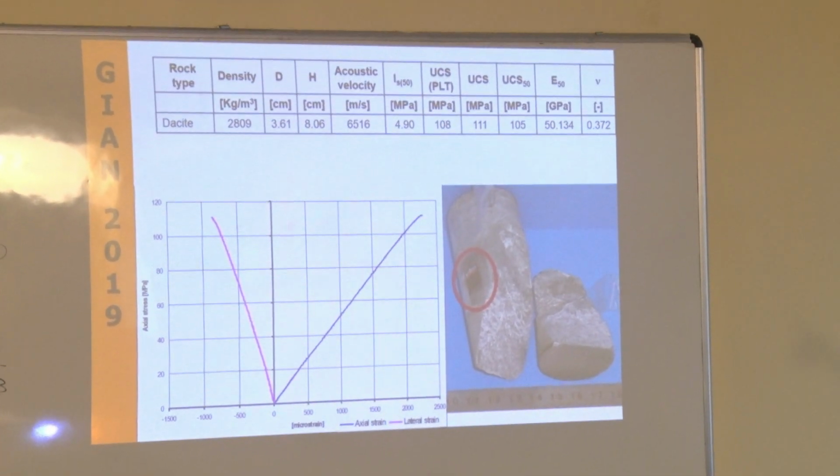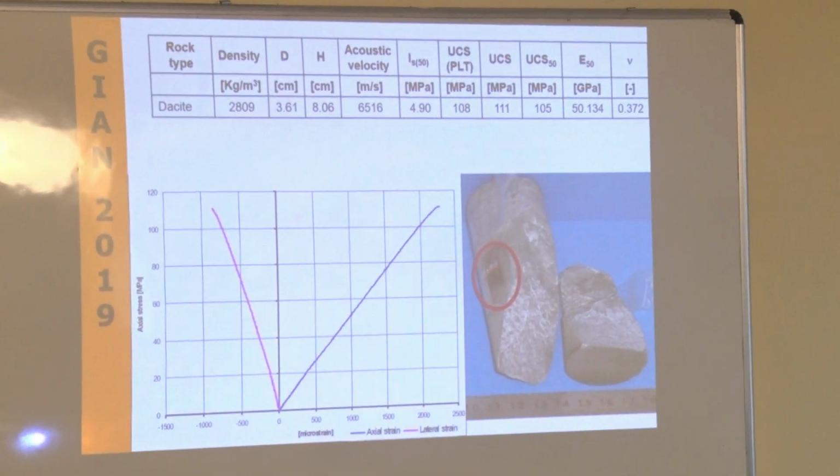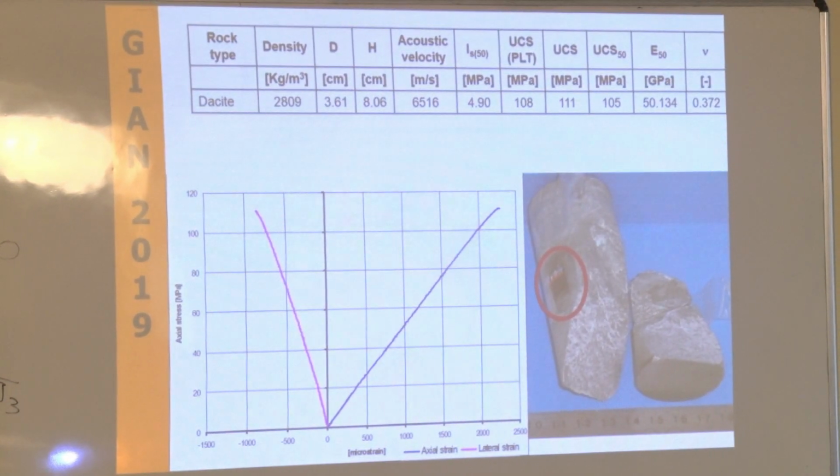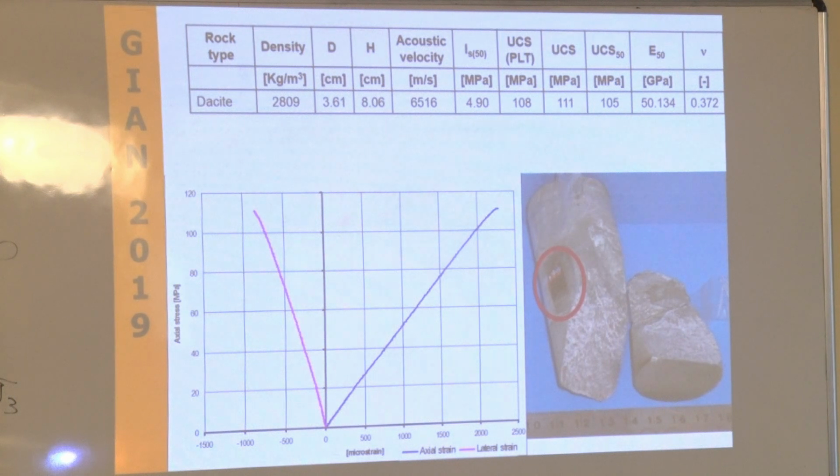So that particular sample is telling you something about your rock, and specifically what is the influence of a rock bridge, so a connection between two sides of a fracture that has not been fully fractured. Okay? So if you need to pick a value, probably you want to use about 130 MPa for the rock, and you're going to use these values to have a better idea of what will be the strength of fractures that have been filled in that particular mass. Okay?